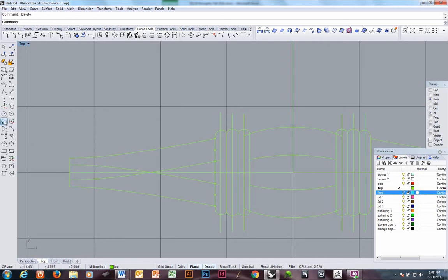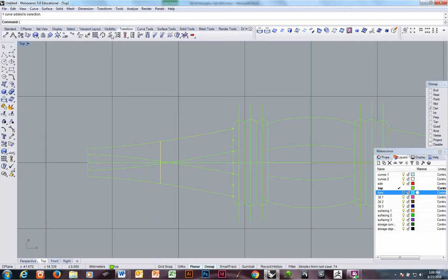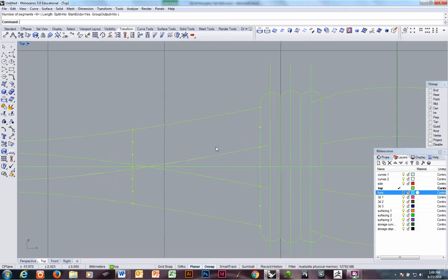The easiest way is going to be circle diameter from there to there, and then a straight line through the center, both sides. Shift key, delete the circle, trim, and divide. Really only need 3, but it's not worth putting in another number. It's just easy to do it that way.